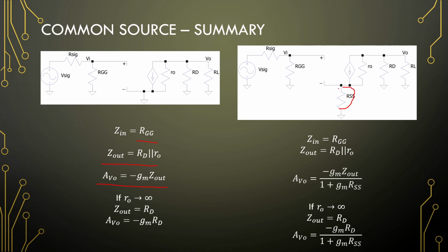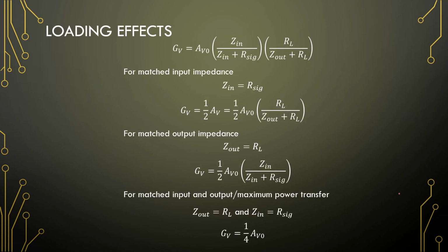Okay, the only difference when adding a source resistor that's not bypassed is that it will have this degeneration effect in your gain, which will help to stabilize your amplifier gain. And again, if R out is moving towards infinite, the equations will just simplify. Right.